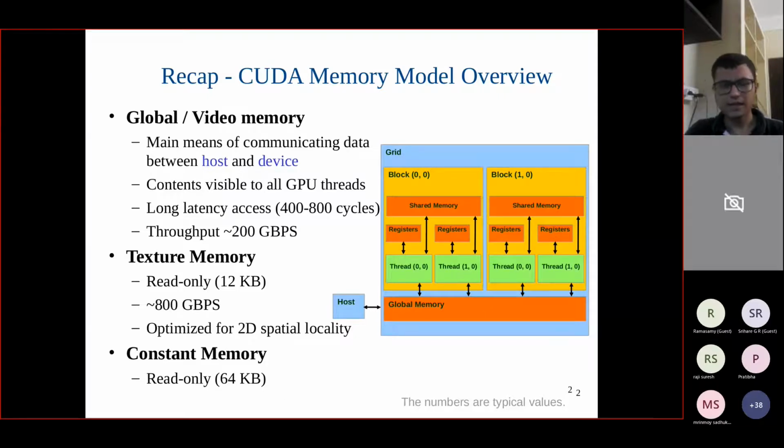As the size is small and they are read-only, they can't be used to store the data on which we perform computation, because the applications we typically run on GPU have very large amounts of data. Instead of storing the real data, we can store metadata inside them, data that keeps track of other data which we have stored in the global memory.